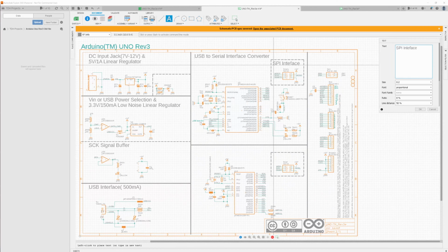This one here is the SPI interface. You can use this in case you design your own Arduino and you want to upload the bootloader with the help of a programmer. The same interface is used here. Then we have the main microcontroller, which is the Atmega 328. This microcontroller is where our source code is uploaded. Everything happening here happens at this microcontroller.